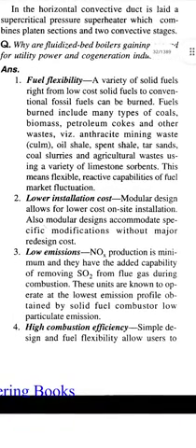Fuels burned include many types of coals, biomass, petroleum coke, and other wastes, viz. anthracite, mining waste, culm, oil shale, spent shale, tar sands, coal slurries, and agricultural waste, using a variety of limestone sorbents. This means flexibility and reactive capability to fuel market fluctuations.